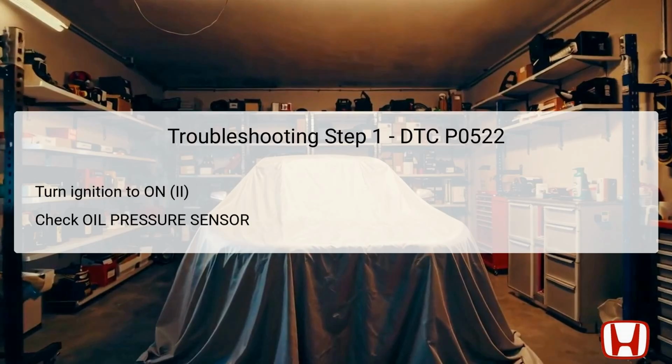The objective here is to monitor the voltage reading from the EOP sensor. If the reading is approximately 0.18 volts or less, you are directed to proceed to the next troubleshooting step. If the voltage is higher than this threshold, it indicates an intermittent failure that necessitates checking for poor connections or loose terminals at the EOP sensor and the ECM. This initial step is imperative for ascertaining whether the sensor is sending accurate data to the vehicle's computer.